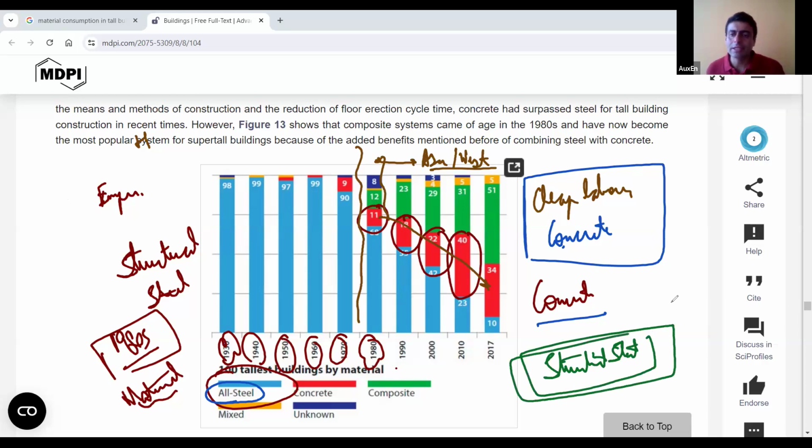And over there, the labor is exorbitant. It is extremely expensive, unaffordable labor they have. So in the Western countries, they prefer structural steel because material wise it may be expensive, but labor wise it is less intensive, and therefore it makes more economic sense to construct in structural steel. If you see the trends in Asian countries, you get cheap labor, so concrete becomes the material of choice.